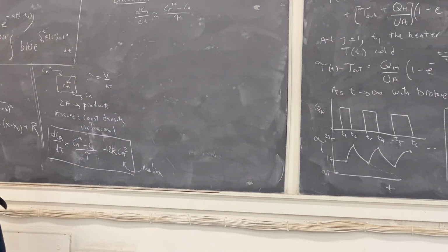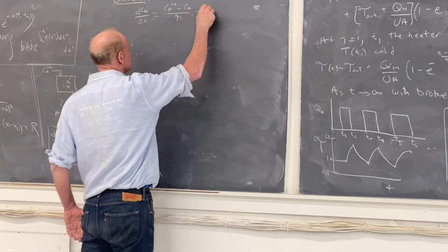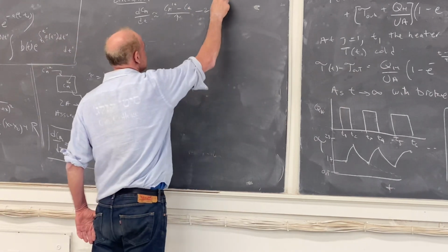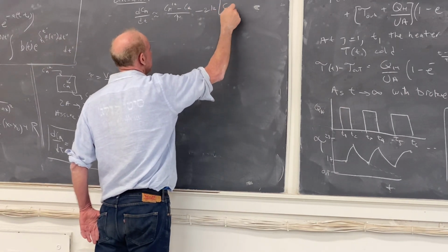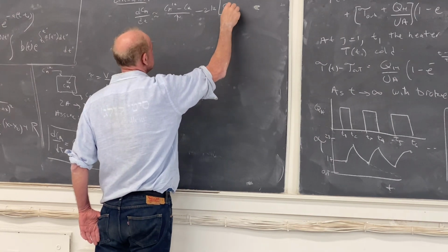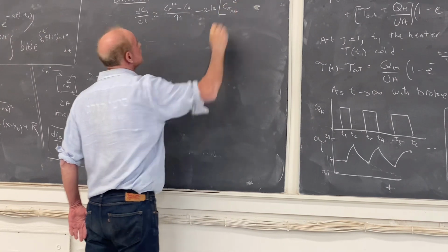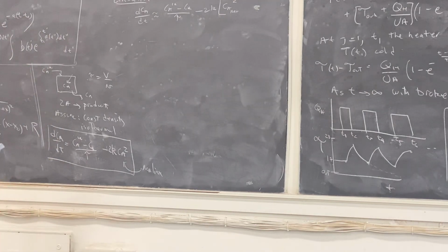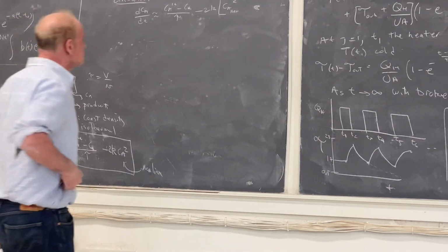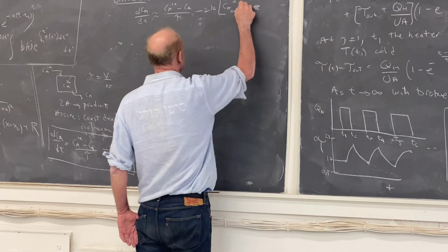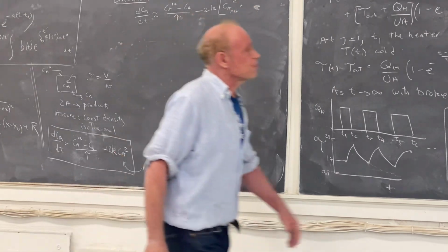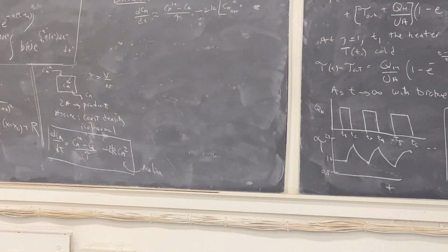And now instead of minus 2K CA squared, I've got minus 2K, and instead of CA squared, I have some CA reference, the point about which I do my linearization, plus the derivative. We have it over here. I don't have to pull that out of thin air, we did it. Plus 2 CA reference over 1 factorial, just 2 CA reference.